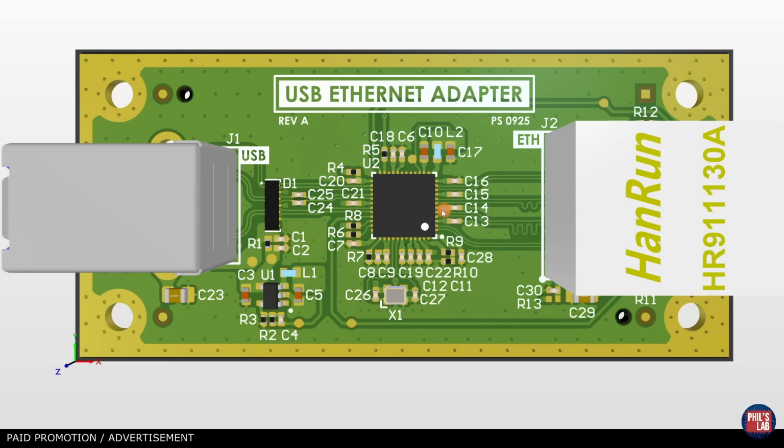The physical layer right in the center is pretty simple to interface with. You just have to follow the datasheet and some app notes. And more importantly for this video, it only requires a single input voltage rail at 3.3 volts to power the physical layer. This physical layer actually generates its own internal voltages in addition as well. But what we want to do in this video is perform a simple DC drop analysis just on this single rail to see if there might be any DC issues with the current that this physical layer draws, and if we get outside of our 3.3 volt margin, given the way this PCB is routed through vias, through traces and planes, not taking any AC effects into account.